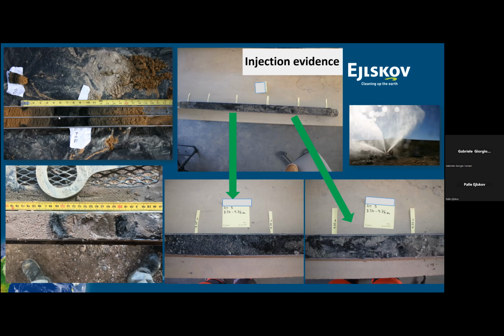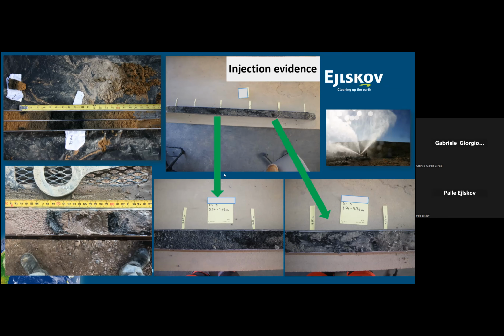This was a powdered activated carbon Boss 200 product applied. This was a Boss 100 product applied. And this is actually an ice core from Denmark, where we had a very tough clay to work with. Here we have a transition zone that shows exactly that difference in spreading depending on how you distribute your product. Here we can see clearly the difference in distribution of the product in gravels and sands, where you have that sort of turbulent mixing, compared to product that managed to enter Danish clay, especially in the Copenhagen area, which is extremely hard.